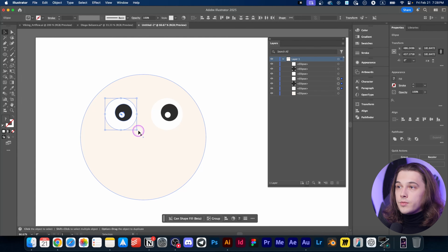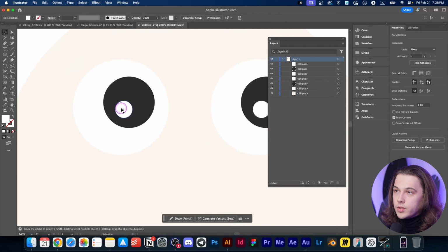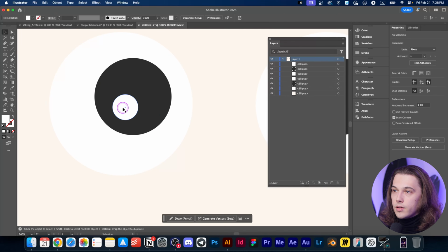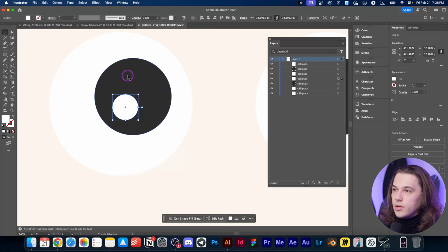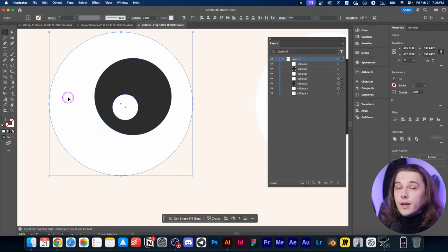So how can you group your objects so you can select them in one click and move wherever you want? That's quite easy to do. You need to select the objects that you want to group, for example this eye, clicking on the first object, holding Shift. Now click over here, click the third object, and now you need to press the combination of keys, Command G.